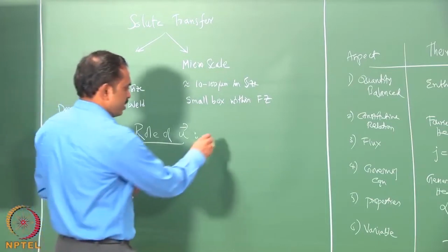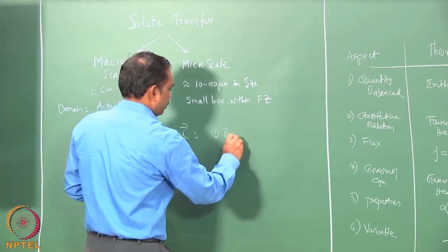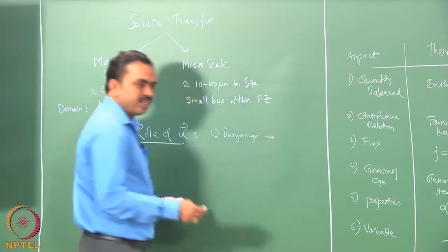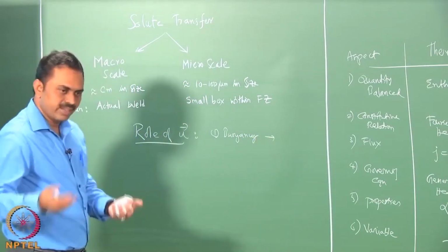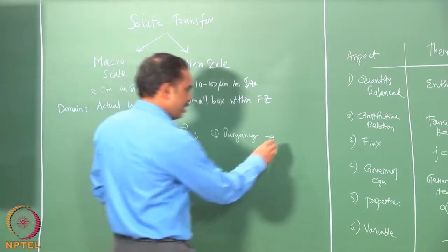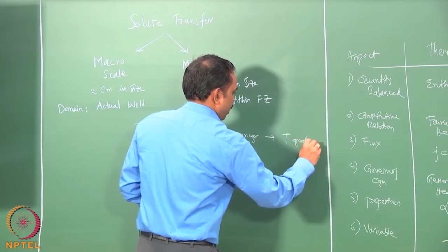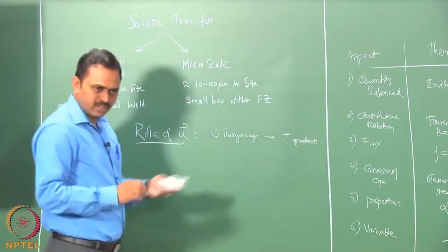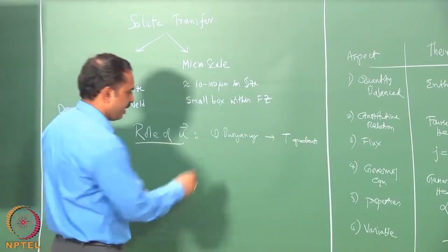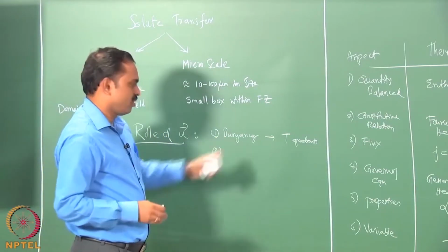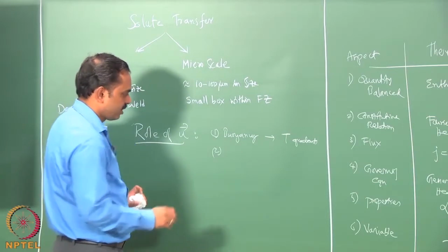The first driving force is the buoyancy, and it is driven by the temperature gradients causing the density gradients, and these do not generally change very much during the welding. Also, the strength of convection is not very high in the buoyancy convection mode.